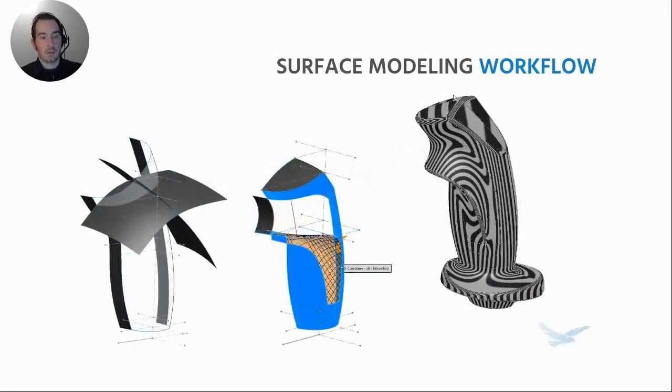And then that's just what it is: constructing a whole bunch of reference surfaces, whether they're sweeps or lofts or boundaries, and stitching together the model one surface at a time until you end up with an end result that is actually a solid in the end. So this gives you a huge amount of control, but it's also a steeper learning curve.